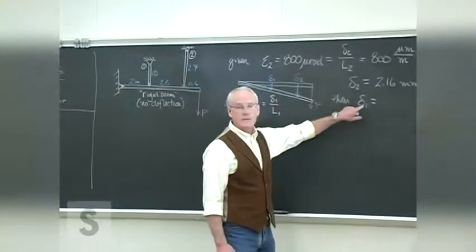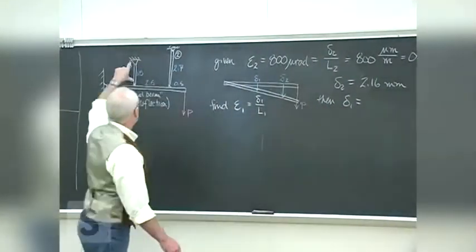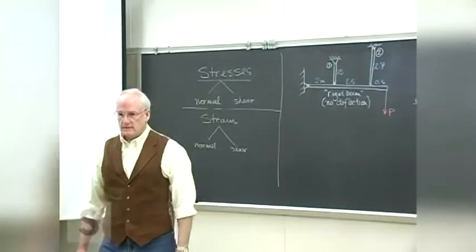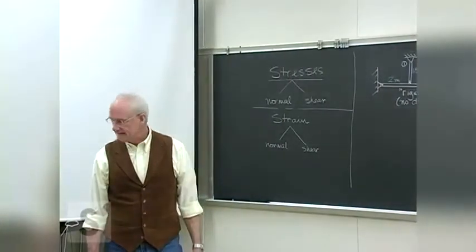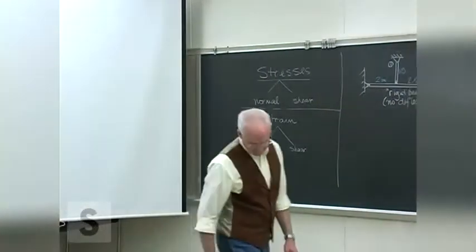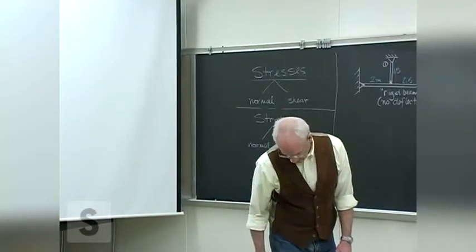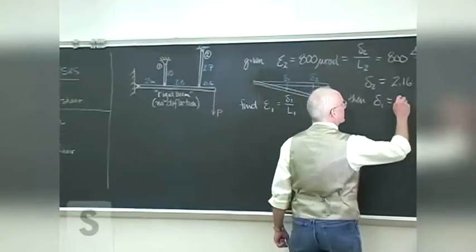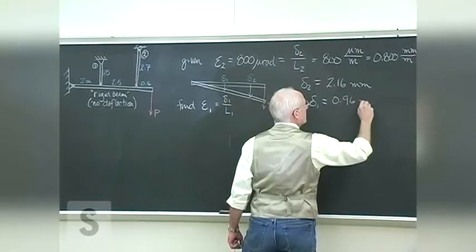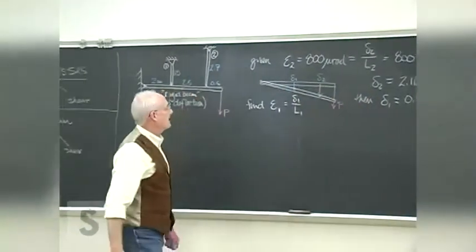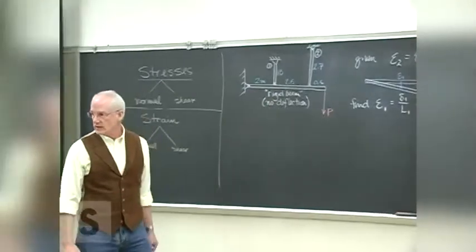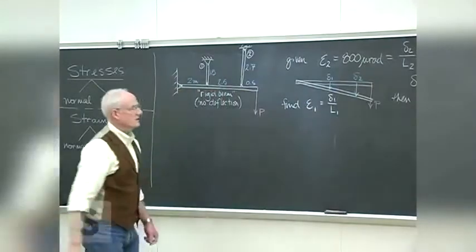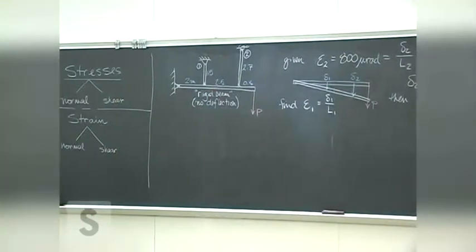What do we have for the deformation of the first support member? Phil, you have that? I got 0.96. 0.96 millimeters? Millimeters, yeah. Agreed? Yeah, by similar triangles. That, again, is based upon the assumption that the beam itself is undergoing no sideways deflection, no axial deformation in the beam, just merely a rotational displacement about the pinned end.